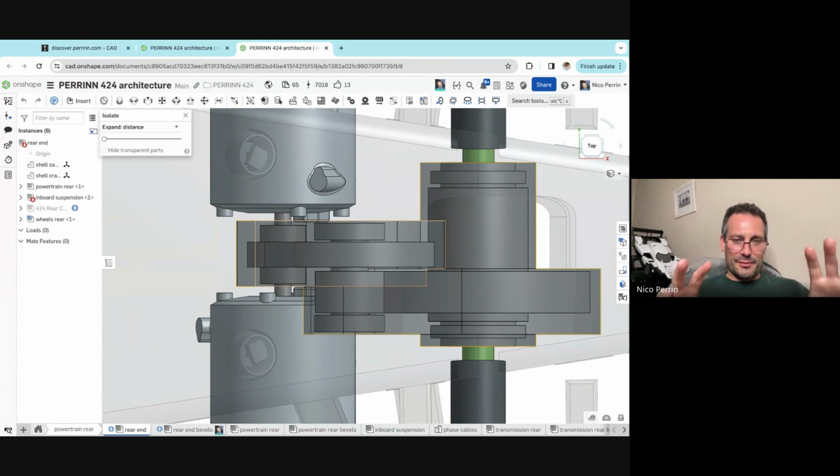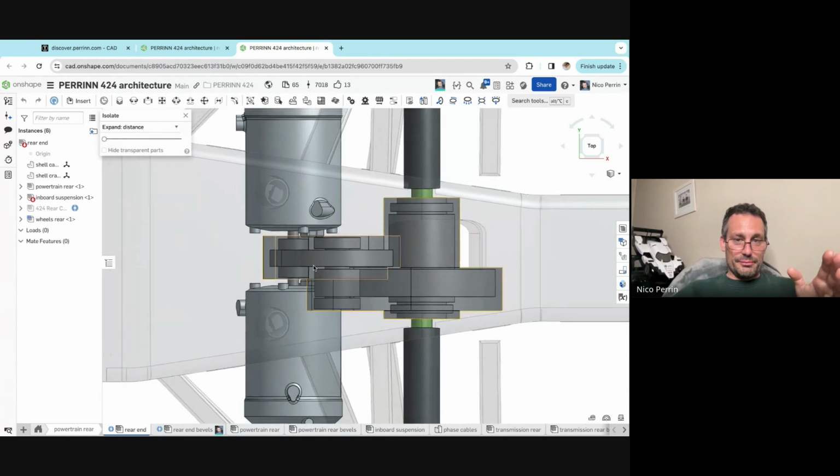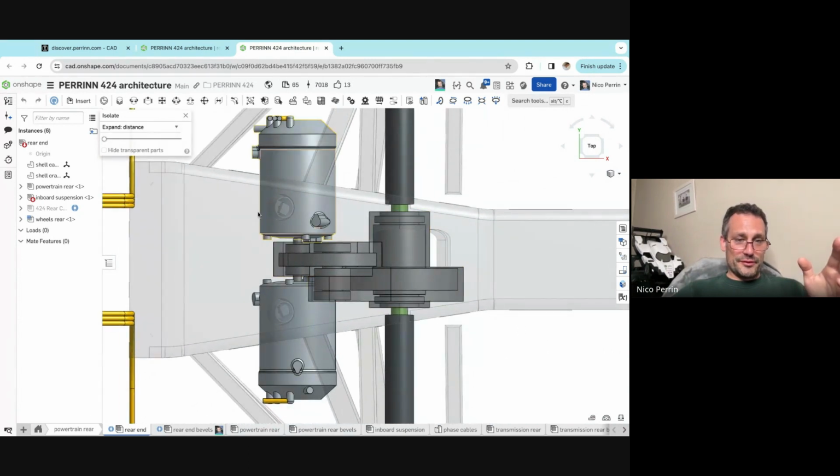For the gearbox, I expect things to move maximum by 5 or 10 millimeters. The reason is the packaging is quite tight, and the location of the motors is important to know, because then we have space for the suspension in front. Everything is quite close together. So I needed to understand that from a packaging point of view.